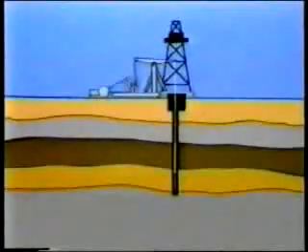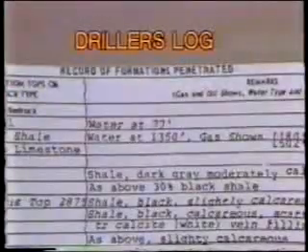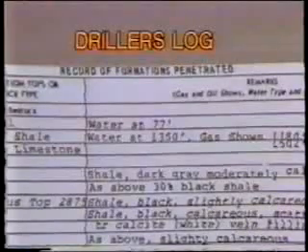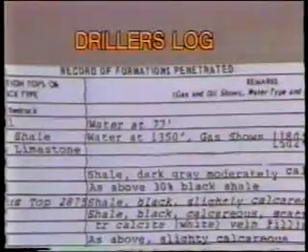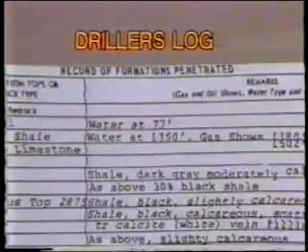There are holes today that are still sunk using cable tool drilling methods, although rotary drills are more common. The cable tool consists of a wire rope suspending a cylindrical bit with a chisel-like end. This is lifted and allowed to fall back to the bottom of the hole repeatedly. The resulting rock chips are removed with a baler. Now, these cuttings are recovered and significant formation fluids are sampled after each baling with the data recorded on what's called a driller's log. Since the new hole rapidly fills up with chips, this usually occurs every few meters. So there is no lag time, and the depths recorded are very accurate.